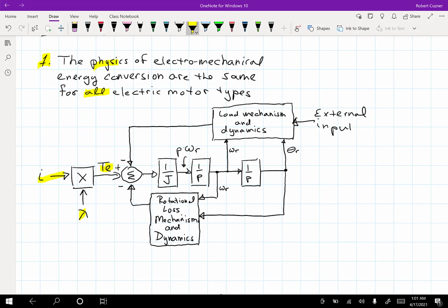working against a load torque, the torque associated with the losses on the shaft. The resultant summing of that torque is going to result in an acceleration of speed. So when the acceleration of the speed is zero, the electromechanical torque minus the load torque and minus the torque loss is zero. There's always an inertia associated with the acceleration, and then we have a resultant speed.